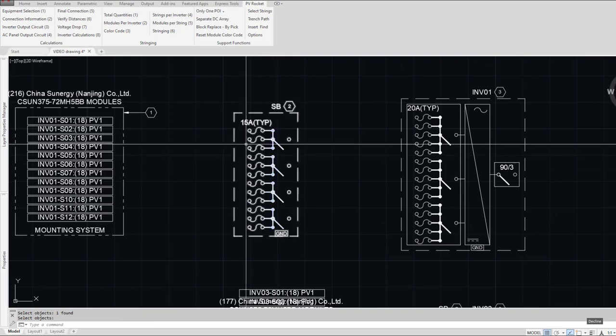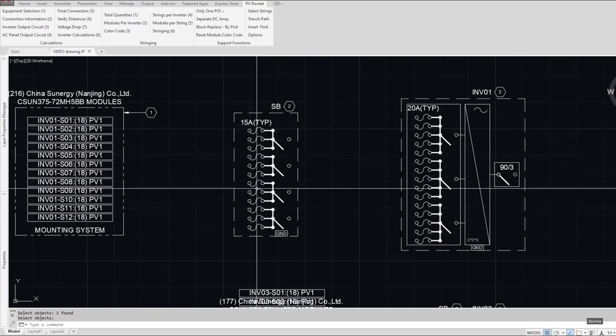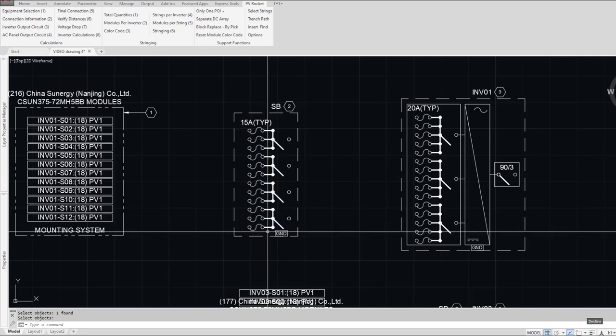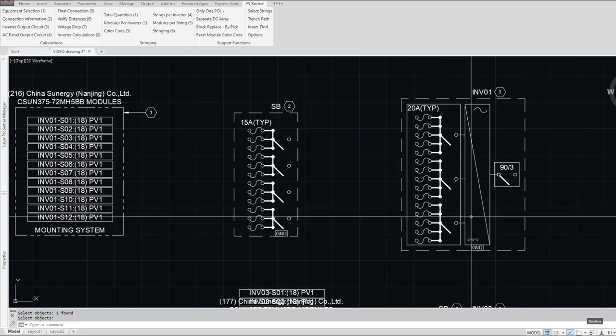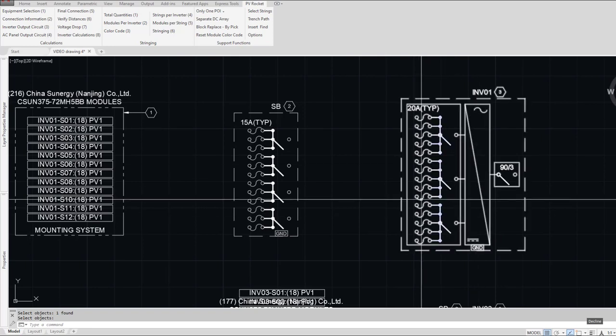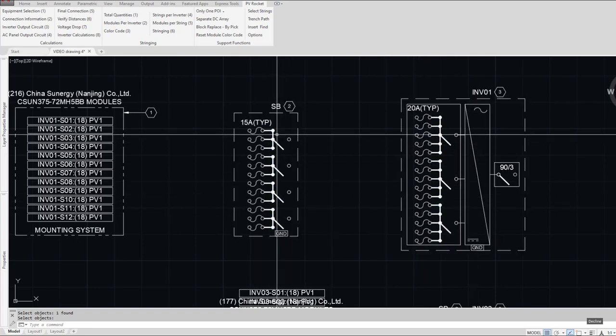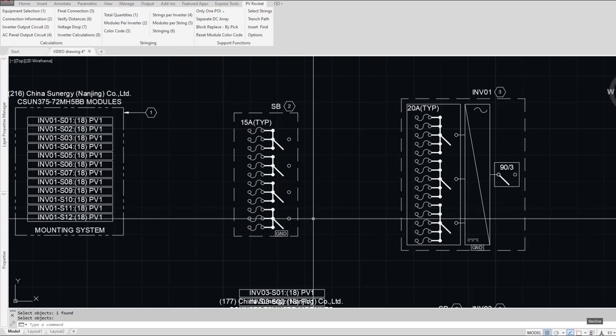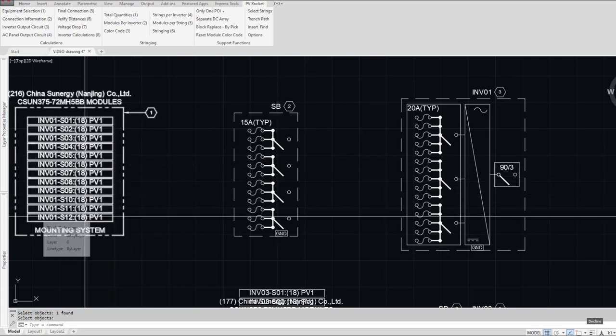But just taking it at face value that this is a DC string combiner that has 4 different separated sets of inputs that each receive 3 strings. Well, we only have 3 trackers in our inverter, so we probably wouldn't want to use all of these, but we would have to because we got 12 strings.